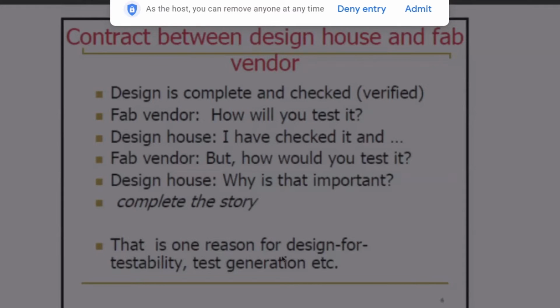Yes, right. ATPG, the D algorithm, the PODEM algorithm, these are the part of test generation, and they have different algorithms. DFT is the part where we have categorized the designs, and we have different methodologies for those designs. There is a relation that for these types of DFT we will use these types of algorithms. So in the next part of the course, units two and three, you will see these things in detail. If you follow the book, the electronic testing book by Bushnell and Agrawal.